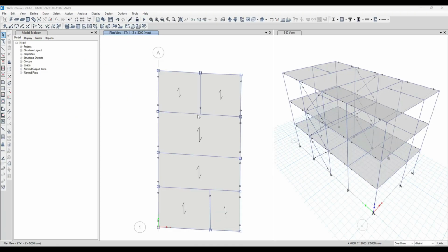I've just opened ETABS. As you can see, we have braces in our y direction and a moment frame in our x direction. The overstrength coefficient in the y direction, where we have braces, is 2 according to ASCE, and the overstrength coefficient in the x direction according to ASCE is 3. To control the columns for the amplified earthquake just for axial load, we have to deceive ETABS.